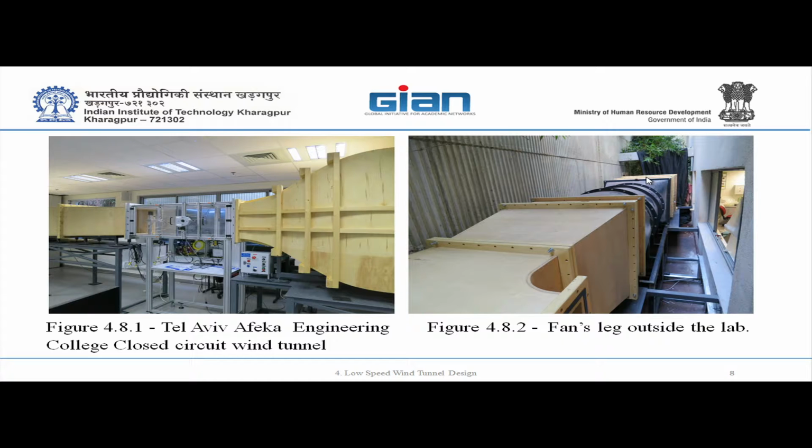So you want it to be fairly downstream. Now, if you put your model in the middle of the test section, you have to go further downstream. So that's why 2 even is not enough, because once you're in the middle, you are left with one length only, and sometimes it's too close. So 3 would be enough.